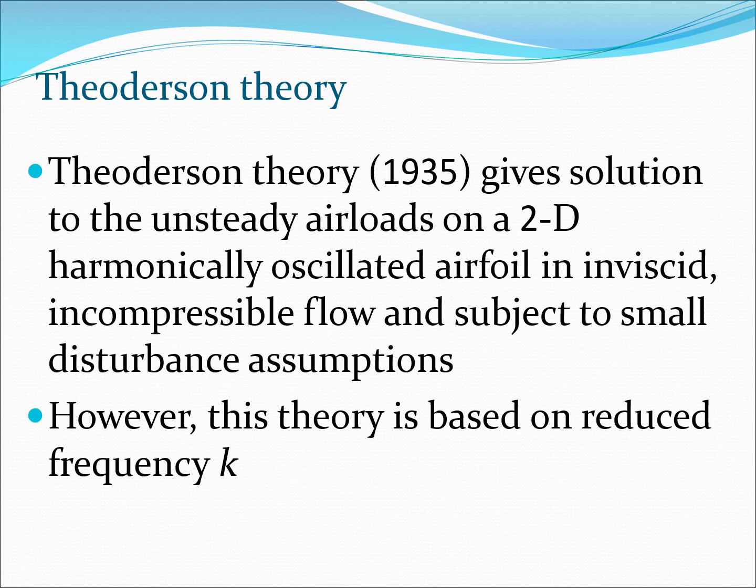You can find it in many books on unsteady aerodynamics. But this is very much developed for fixed wing, because in fixed wing you can realize that V is very well defined and frequencies are very well defined, especially as far as an airplane is concerned. It always flies at a certain velocity V, which is its general cruise velocity.